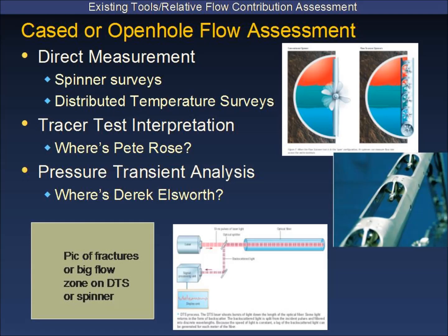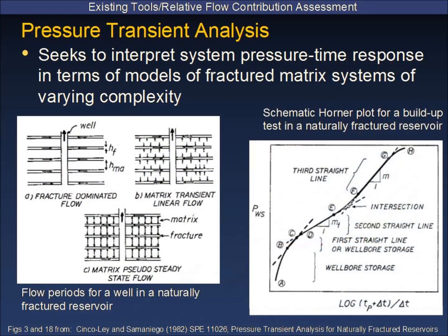Tracer tests are not routinely used in the oil and gas industry. Even using them to interpret residual oil saturation is above the expected competency of most of our staff. So where's Pete Rose? Are you around here? There you are. Okay, good. So if you have anything you want to know about tracers, I would certainly refer you to him. We do use reactive tracers to assess residual oil saturation, and we do use non-reactive or conservative ones to investigate interwell transit times between injectors and producers, but this is not commonly done. And Pete does much more complicated things than that, so I look forward to hearing what he has to say.